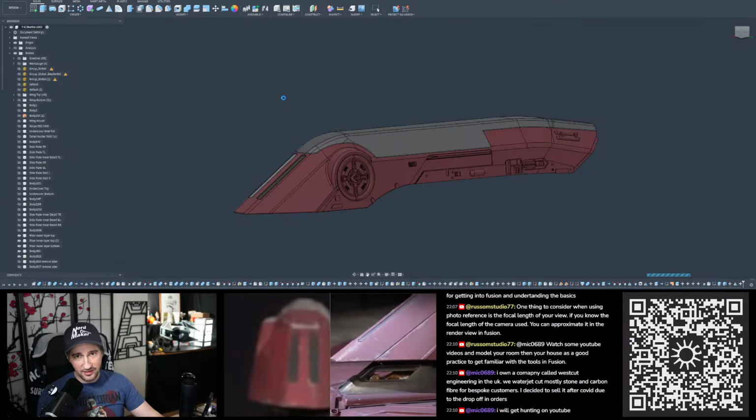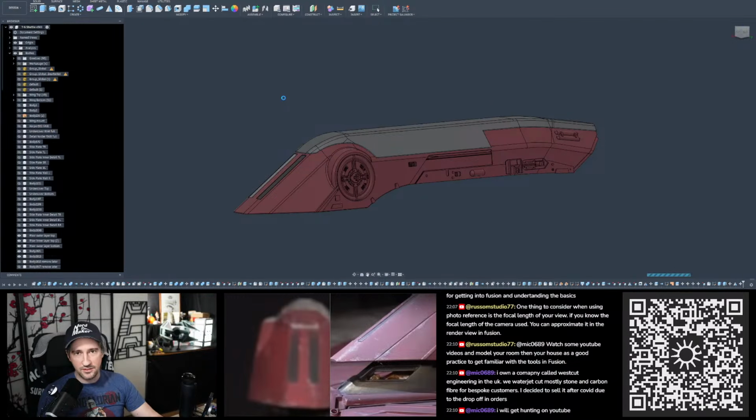That's a tip I can give everyone who is working with CAD software. Save as often as you can, even if you have to set a reminder. Because working for, I don't know, 2-3 hours straight without saving and then having the program crash and you lose that progress, that's a huge freaking bummer.